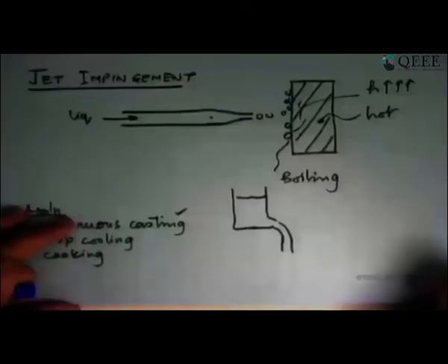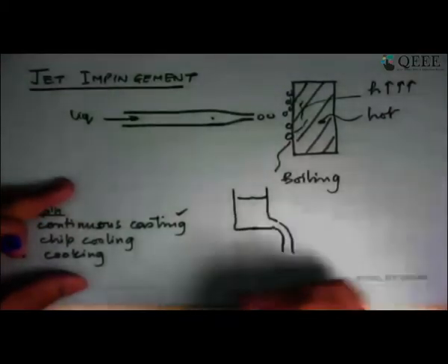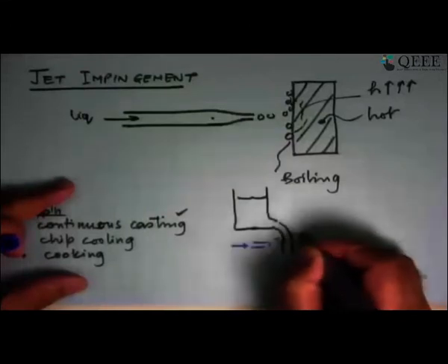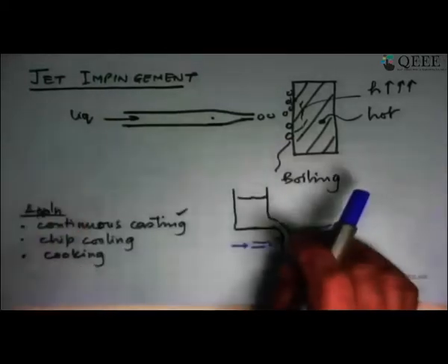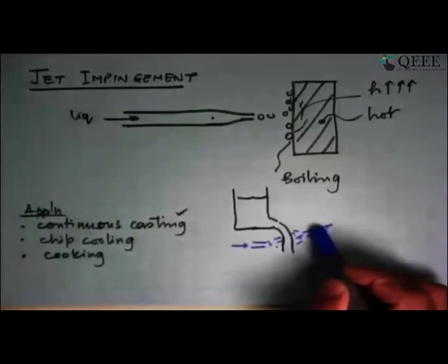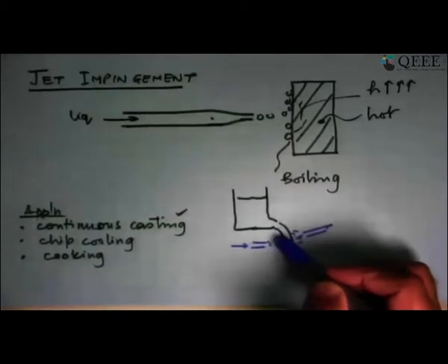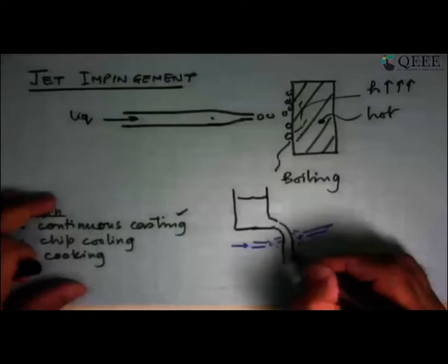Well, instead what happens in continuous casting, and this was a process that was invented just after World War II, was that you take this thing coming here and then you pump in a spray of water onto this. So liquid steel is about 1550, 1560 degrees Celsius. This water is at room temperature. So you got water coming and hitting it with a huge temperature difference. There's a lot of boiling going to take place. It will cool this liquid very fast. And as this liquid gets cooled, it falls down.